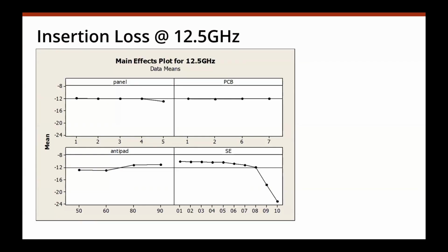So what I wanted to show here is that the effect of via stubs is real. You can measure that. There's no way around it. So if you're talking about frequencies where the stub length is already affecting your design, you really need to think about how to avoid these via stubs, either by back drilling or by going with a sequential design.